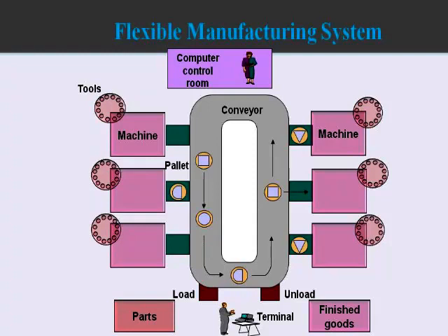As and when a particular part reaches a machine, it is placed on the machine with the help of pallets. Pallets are automatically placed with automatic setup dock pins. The pallets are located on the machine. So as and when a particular part is loaded on a machine, the part is read, and accordingly the program for that part is loaded, and the machine starts processing that program. This goes on.